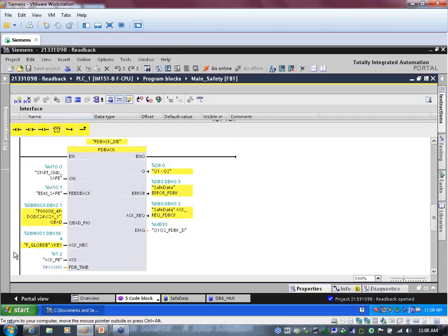And again, I've given it the failsafe 1 to always require an acknowledgement if I should get an error in this function block. Again, it has a diagnostic byte that I've chosen to take out, and I'm going to show you in a minute how we're going to view those bits.